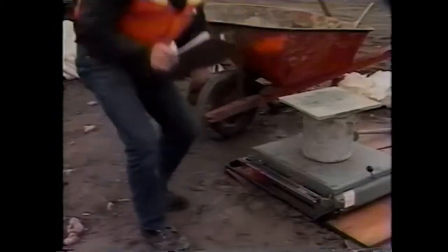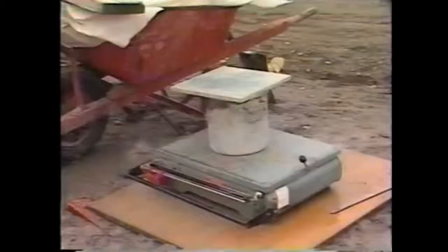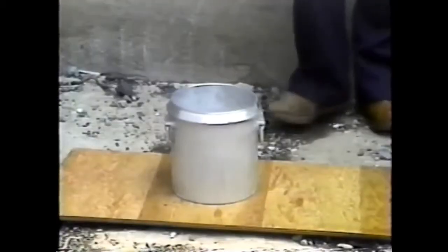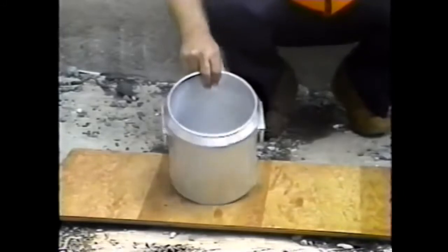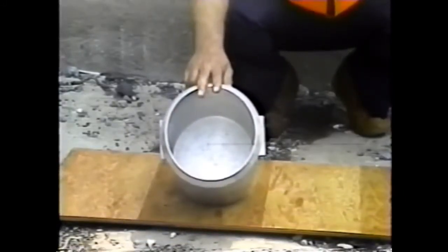The unit weight, or density, is determined simply by weighing a known volume of the concrete. The same equipment used for air content testing is needed, as well as a measuring container, or measure, a balance or scale, and a strike-off plate. The balance or scale must be accurate to within 0.3% of the test load. The measure must be a watertight cylindrical container whose capacity depends on the size of aggregate used in the concrete.